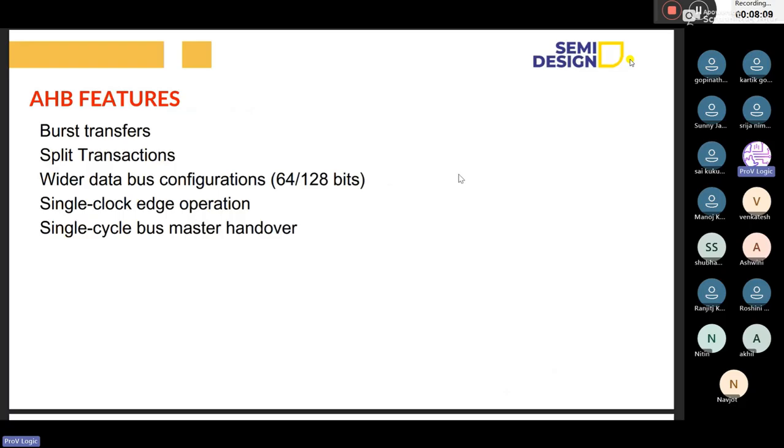And also it has different phases: address phase, data phase. Okay, in APB protocol we don't have the phases. Okay, what signals do we have? Just a clock, reset, select signal, enable signal, and separately P address, P write data, P read data, like that. We have no separate phases.